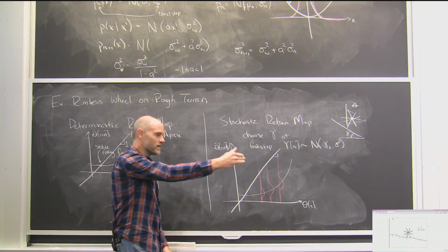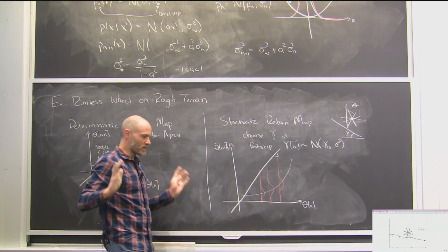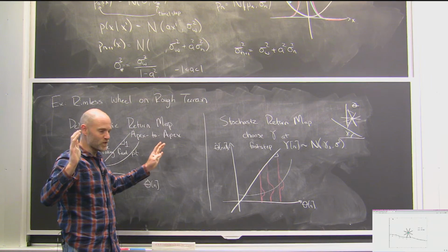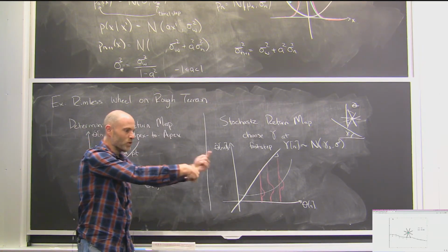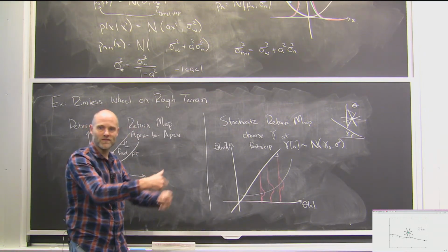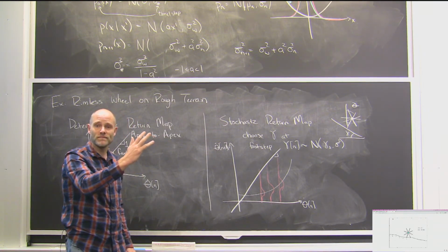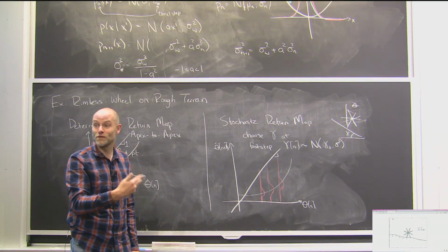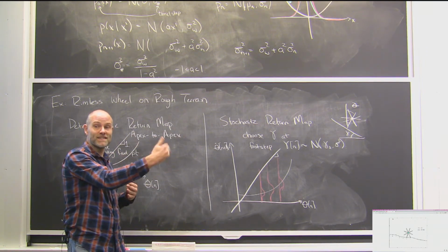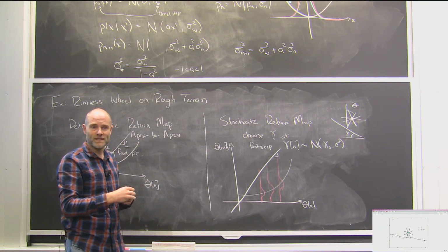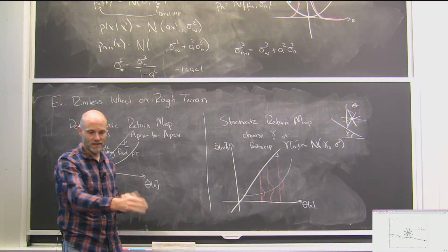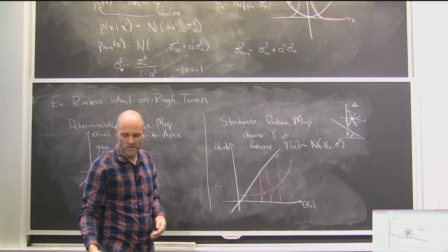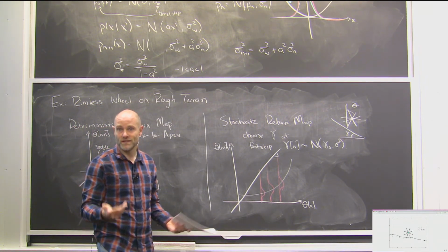If I watch that system roll out, if I were to run a bunch of them in parallel, like people do in their robotics paper videos now, right? More and more of the rimless wheels would come to rest. Some of them would keep going for a very long time. Actually, it's very interesting to compute the mean first passage time. That's a meaningful metric here: what's the mean time to failure of the rimless wheel? Okay, and they can be really big numbers, depending on your distribution of your terrain. All of those things you can sort of compute, and those are the meaningful statistics of these processes. But eventually, it will fail.